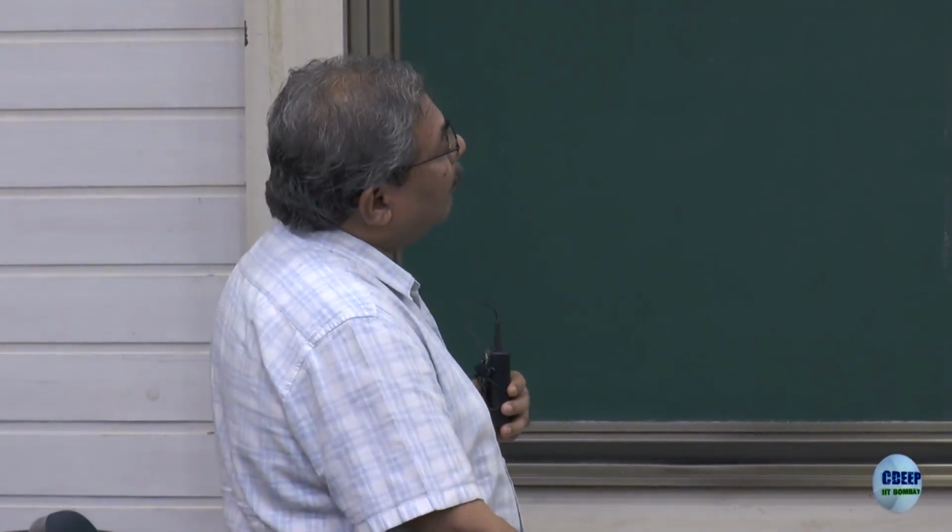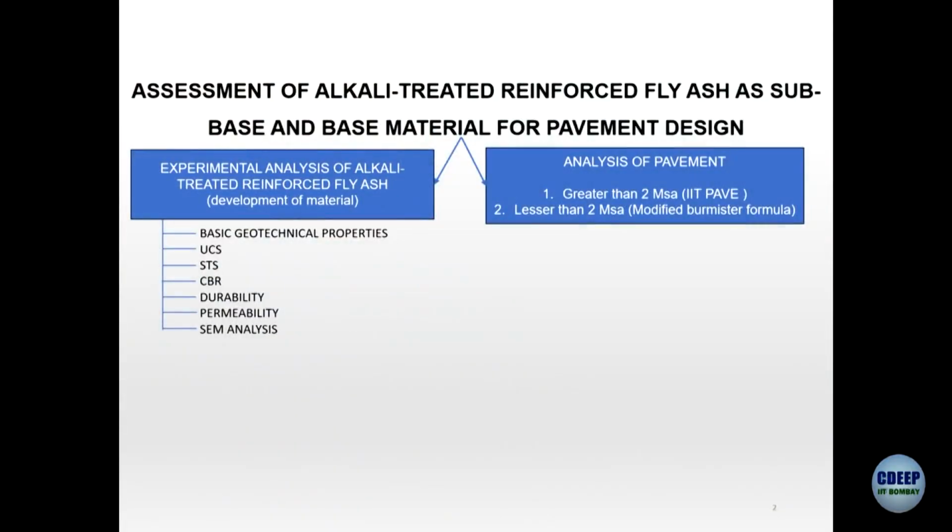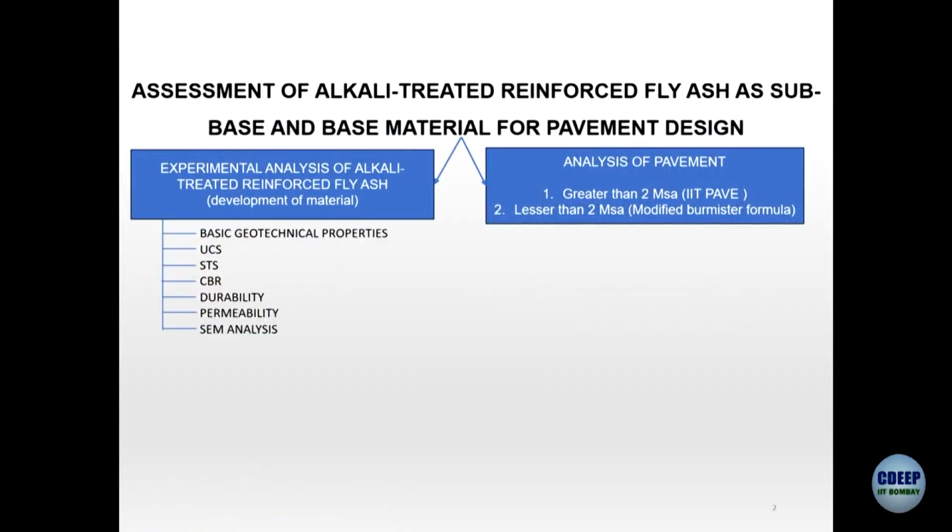By virtue of their fundamental characteristics, most of these grains of fly ash are silica, quartz. And quartz, when it reacts with hydroxides, will etch and release silica, and silica is nothing but the silica gel, which is the gel you create when you create concrete. So the more the gelling process occurs, the better the bond formation.